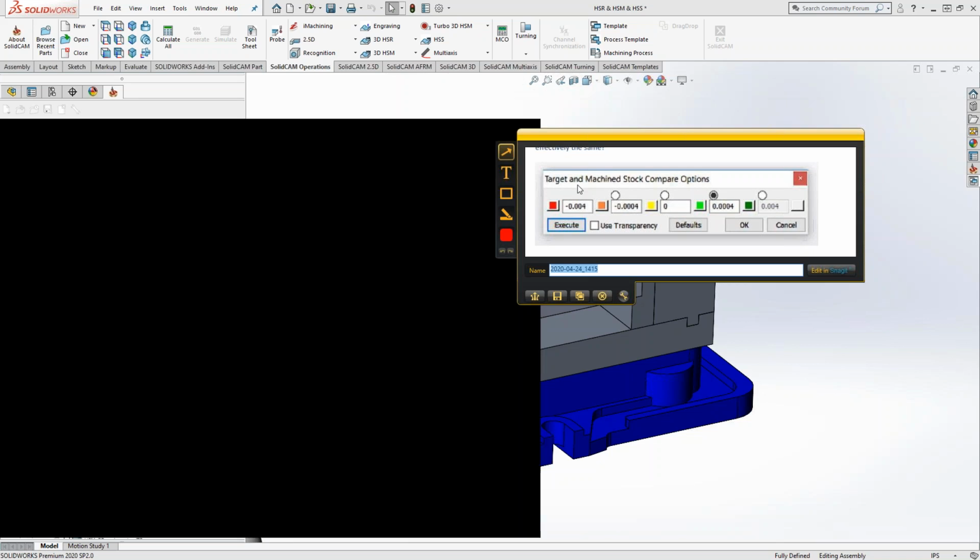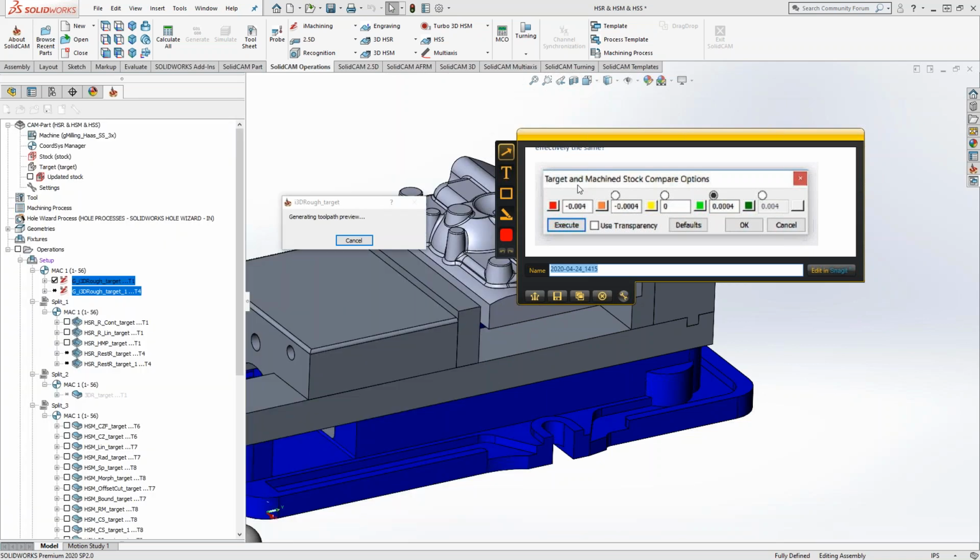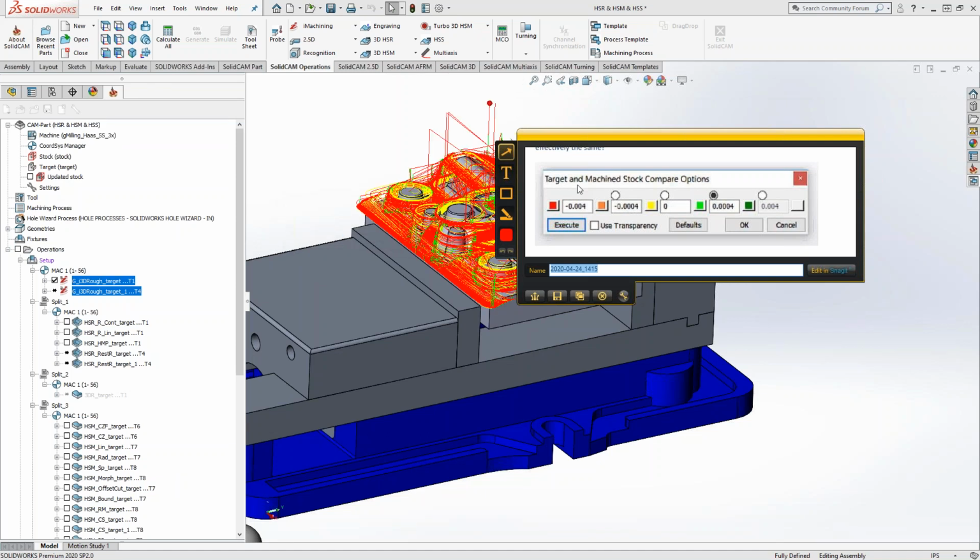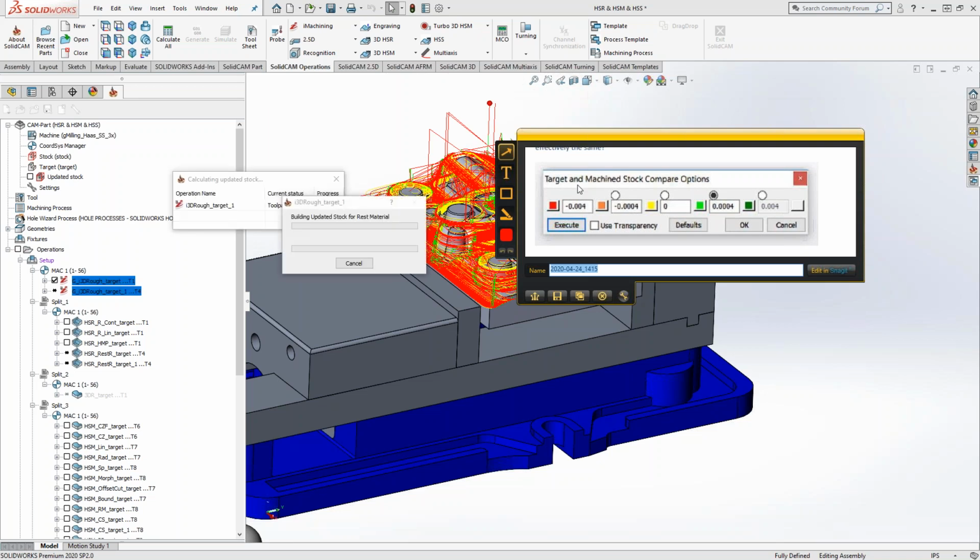I think we advise them to maybe keep it at 50 thou or 100 thou, only because of just how big the thing is. So rather than render that thing right down to 4/10 or a thou or whatever, you just keep it super coarse. You can check what you need to check, and then you've got your solid verify results. You can confirm at least you're not going to gouge to a certain level.